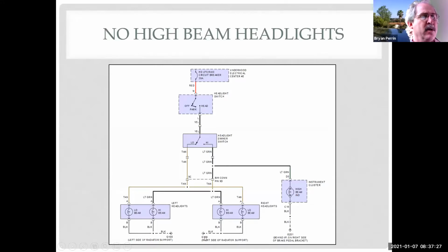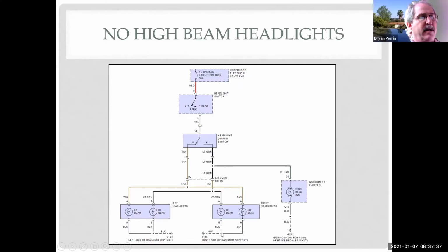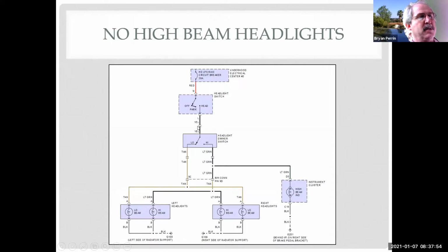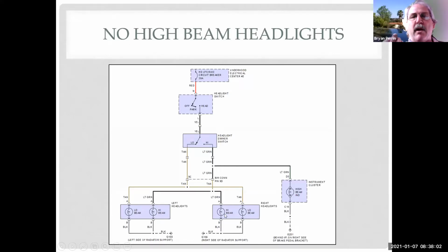And that's why I'm trying to. So the ground, right? This ground symbol goes all the way back to my battery. So here's my ground symbol, and here's the wiring that comes over and attaches to both my headlight bulbs. I have the power that comes down, and then it goes through my load and over the ground. If I go on the high beam side, I come down through the light bulb to ground. So they both share the same ground connection.